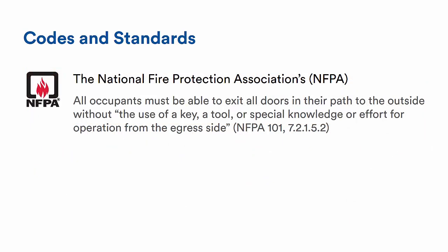So the National Fire Protection Association, known as NFPA, is the life and safety Bible. Virtually every building, process, service, design, and installation is affected by NFPA's 275 plus codes and standards. The Golden Code is specified on the slide, which essentially says that in general, every person within the building must be able to exit all doors in their path to the outside without the use of a key, a tool,